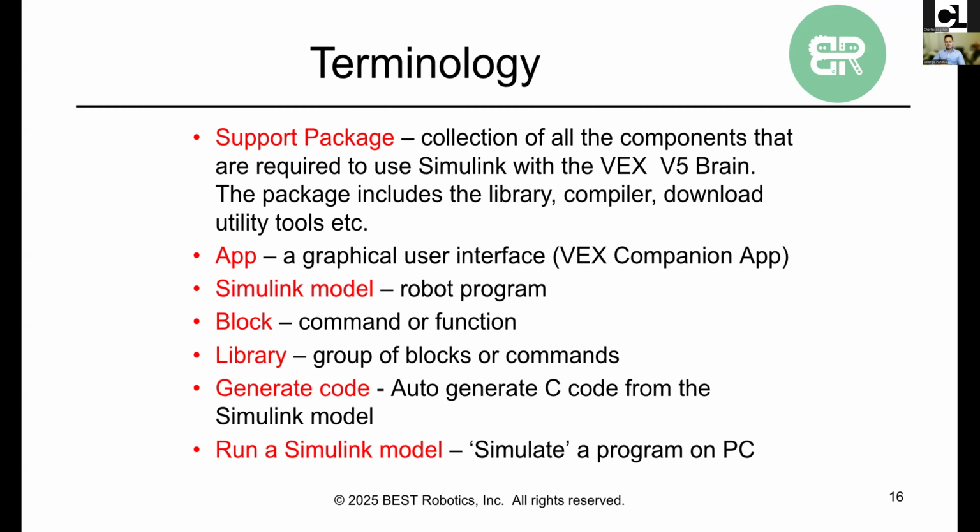There's something called a VEX companion app, which I glossed over in the installation slides, but it is a very valuable tool that allows you to more graphically design a lot of these Simulink systems. It is not compatible with the 2025 version of Simulink. So when you request a license and download, make sure you download the 2024 version. That'll give you access to all the features that you need, and keeps you backward compatible with this companion app.